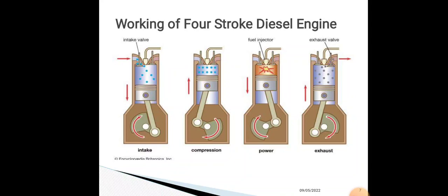Due to the higher pressure in the cycle of operation, the CI engine has to be stronger than an SI engine for the same output. This results in a CI engine being heavier than the SI engine. However, it has a higher thermal efficiency on account of its higher compression ratio, about 18, against about 8 in the SI engine.